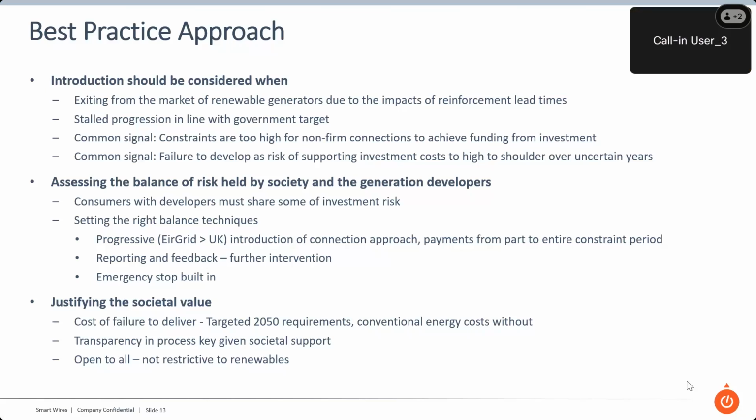And maybe that's referring to the stability problems or control interaction problems or oscillation problems. I'm not sure. Yeah. So yet again, if you're looking at the outcomes, if you've got a high level of renewables coming in, you're getting a reduction in system strength. You've got a higher risk, obviously, of having controller interactions and or things like subsynchronous oscillations occurring. Some of the tools I mentioned, like the GETS technology, can manage that, and it can mop up those problems as they occur almost in real time.